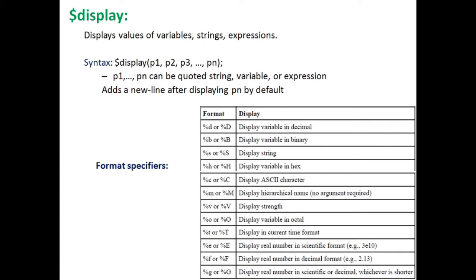So operations such as displaying on the screen or monitoring the activities of all your net variables, and if I want to stop the simulation or finish the simulation, we generally use the system task. So $display is the task for displaying the values of your variables or strings or input output ports or expressions on your monitor screen.